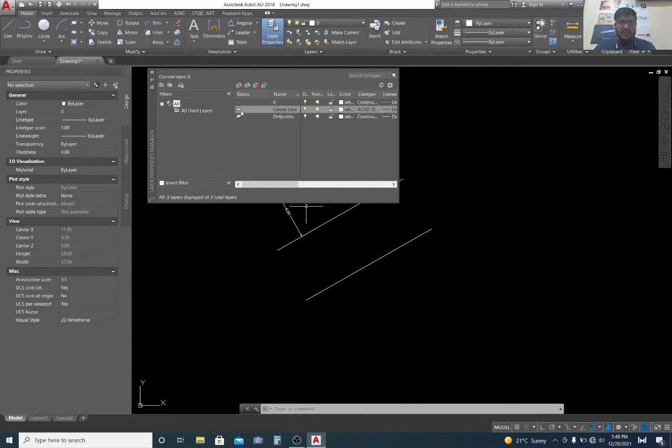Okay, now what we will do, we will make this tick. You can see this tick, the right mark, on the 0 layer. For making this layer our default, we make some settings. We made the white color, we made the line type, right? We'll double click this one. When you double click this one, you have selected this current layer. When you are drawing any object, this layer will be activated. So when you are making a circle, arc, whatever, this layer will be activated.